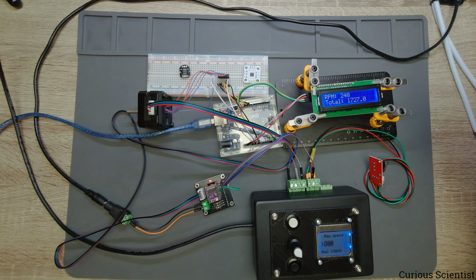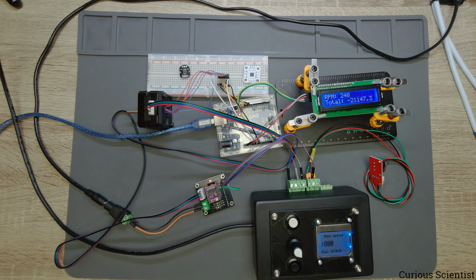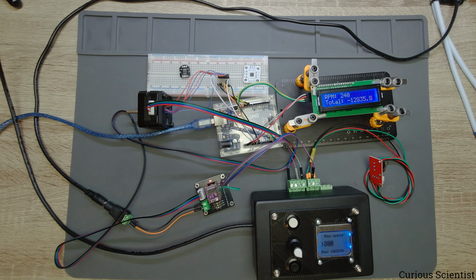But as long as it works, and as you can see here, the RPM is 240 as we would expect from the doubled speed. So just to go through the mathematics of this thing, we want to move 800 steps per second based on these settings. We have 200 steps per turn in the microstepping setup, which means that we are doing 4 full turns on the shaft per second, and then 4 times 60 is 240, which we see on this display. So you can see that it works properly.